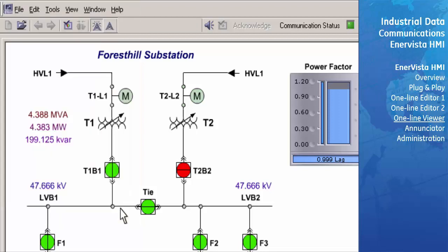Control. In this schema, there are 6 manual indication controlled breakers whose states are manually set in the viewer. There is also 1 automatically controlled breaker whose state changes automatically within the viewer to reflect the value on the device. Finally, there is 1 control breaker whose state is changed on the physical device via commands sent from the System Viewer. This state change is also automatically reflected in the viewer. We will now go through the steps on how to utilize these various types of breakers. Let's start off with the manual indication controlled breakers.